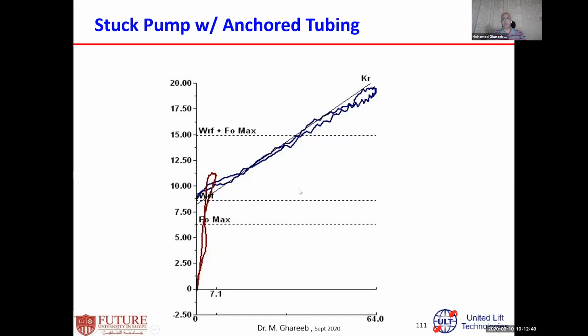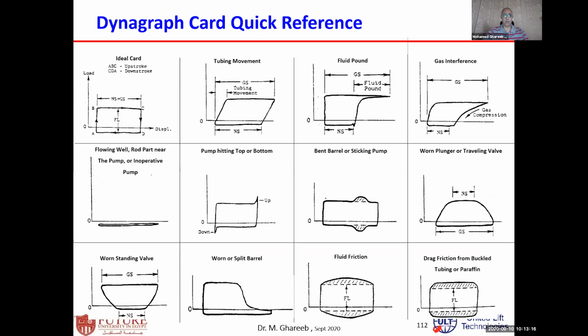However, I showed you all this is an actual dynamometer card. In order to understand, you need to know the basics. If you know the basics, you can understand and analyze your actual dynamometer card. But keep in mind, a dynamometer card is not very easy to do. In some cases, you need to analyze more points inside the well.